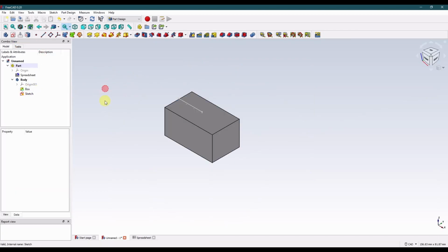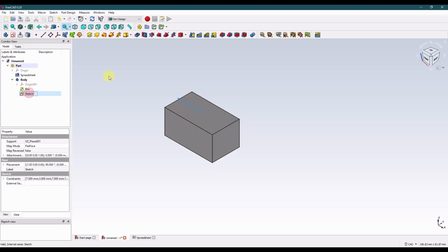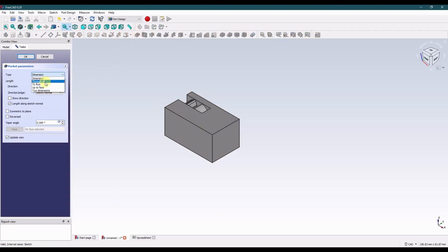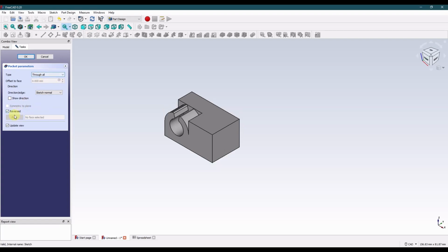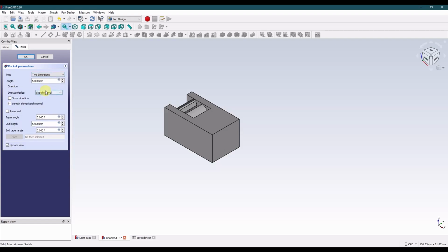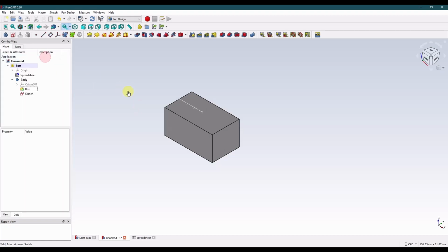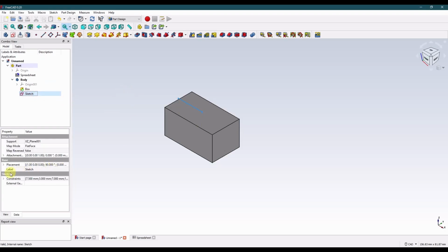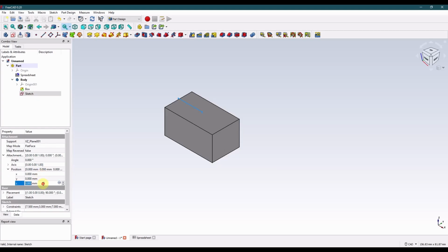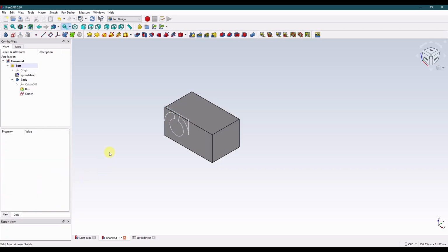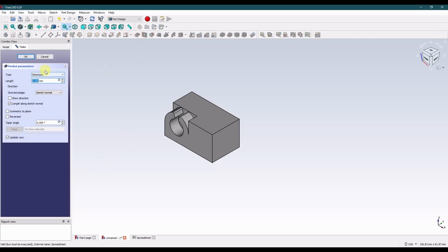Let's click close on that. We can show our box again, and we can do our cut. I did do this incorrectly, didn't I? Let's move this sketch out. I know it's a little bit wonky, but let's just move that out to 8 because it's 16 thick. And then we'll cut that through all.